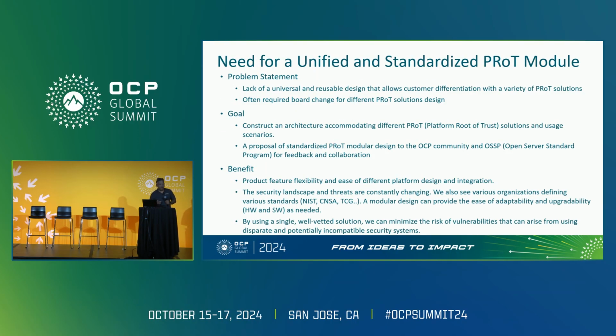Before I go there, I need to define a little bit of the PFR. PFR, by definition, is platform firmware resiliency, which is defined by NIST. NIST gave a compliance spec, and Intel provided an implementation spec. Why do you need a PFR when you have TPM and all those things? Because what TPM does is boot time protection, but PFR is actually T-1 protection. PFR verifies the boot firmware, which is the BIOS firmware, and also the BMC firmware.